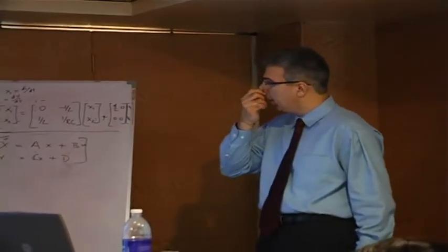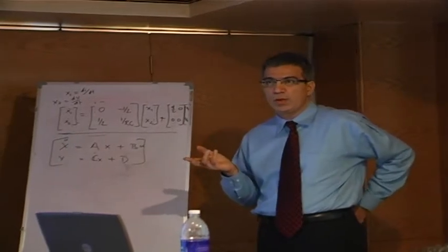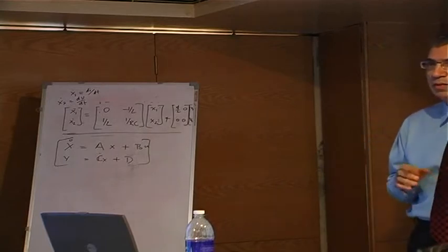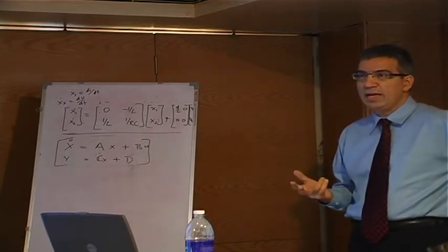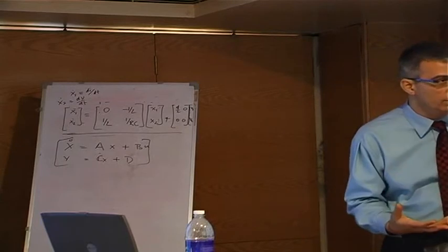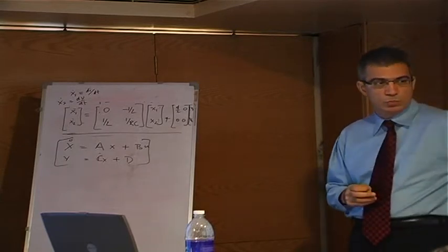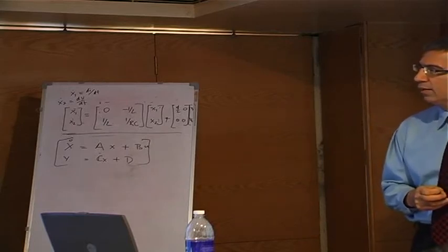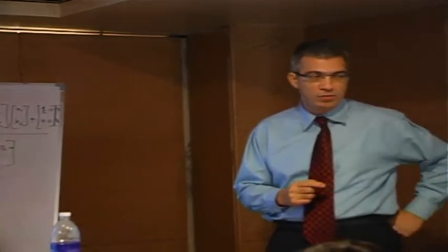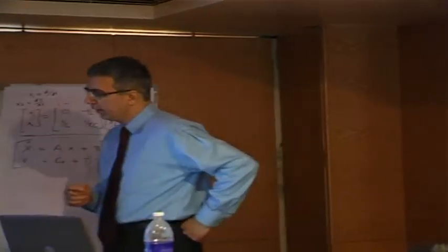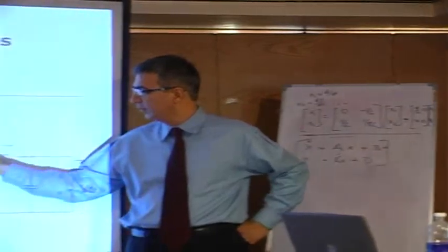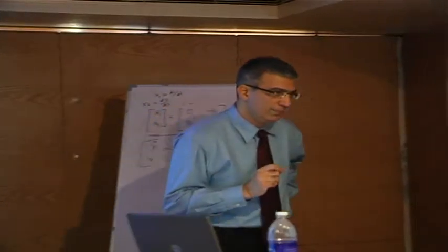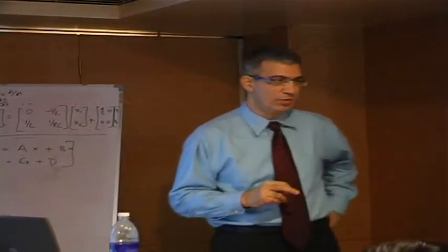Okay, so now this was one of the first attempts at small signal modeling. If we could convert these equations into state variables, then we have a chance of understanding the average behavior of the system. This state variable, whatever is written, is for on state only. This is actually simplified. It's not really on state because we are considering the average voltage at this point of time, which is dV in. So it's sort of a slight extension of the truth.